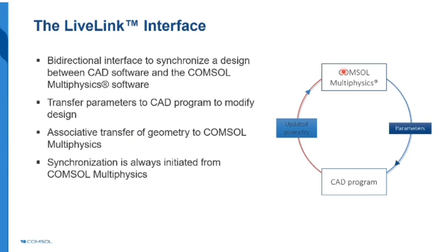For example, if you are running some optimization study, then based upon the solver, your geometry should get updated. Then that geometric parameter will have to be sent back to the CAD program. The CAD program will rebuild the geometry and send that updated geometry back to COMSOL Multiphysics.